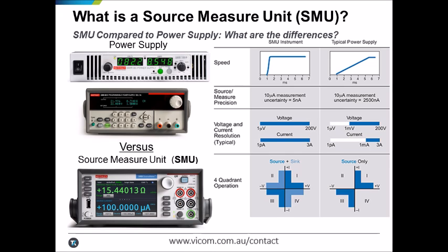Another key feature of an SMU instrument is its sweeping capability. This enables custom programming of the source, delay, and measure characteristics of your test and really boosts productivity. Pulse sweeps greatly reduce the power dissipation within the device, so the effects of temperature are virtually eliminated.